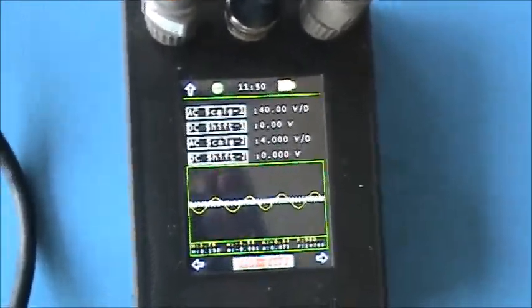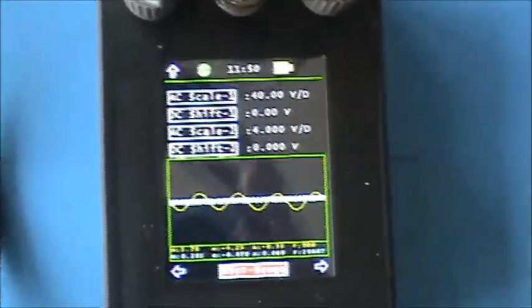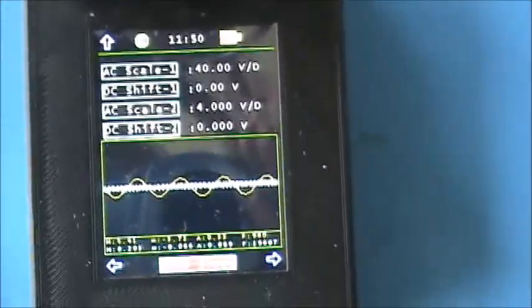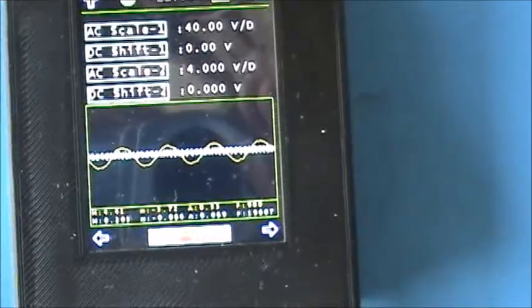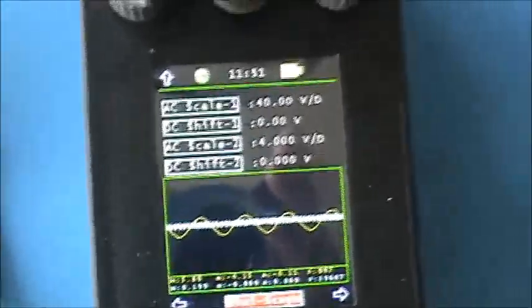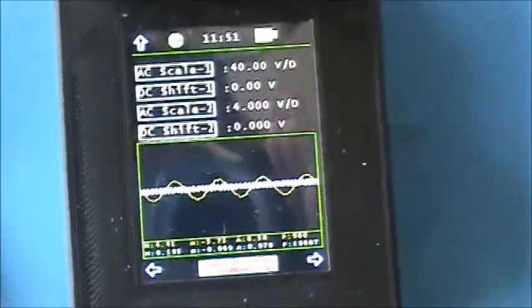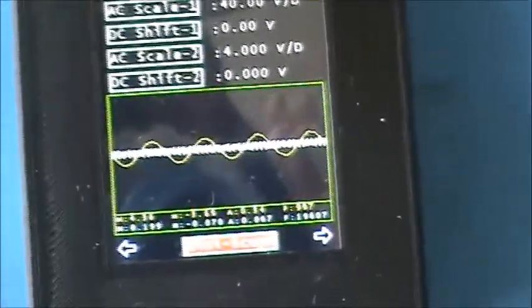The VCO signal, as it appears on the AM modulator schematic, must have sufficient amplitude to allow modulation, around 250 millivolts peak to peak. As we discussed, the VCO signal is not displayed properly because it has a high frequency for the TopNotch meter, but we can measure its maximum and minimum. So we can see the maximum is about 200 millivolts and the minimum is about minus 70 millivolts.